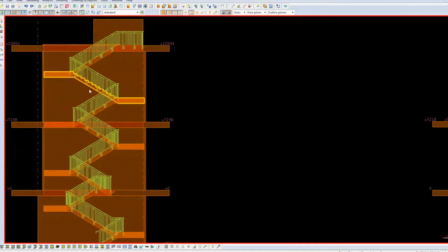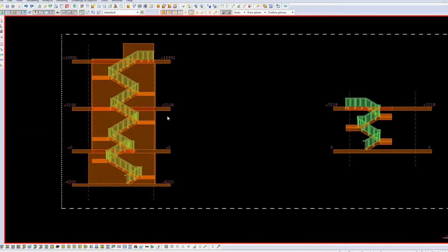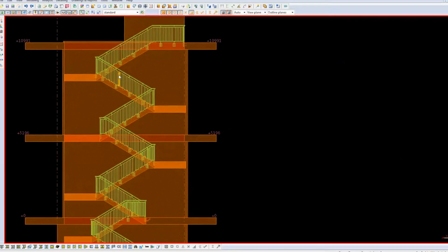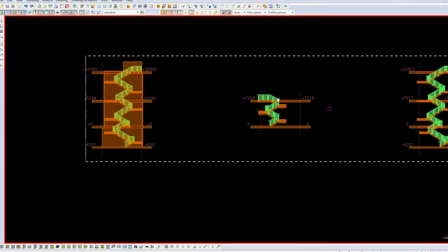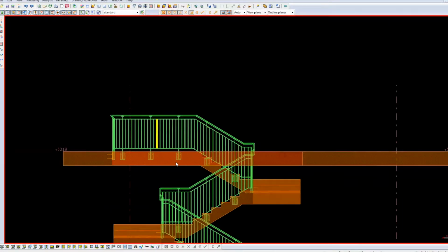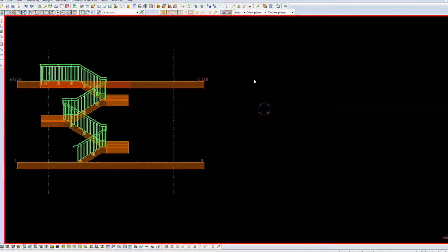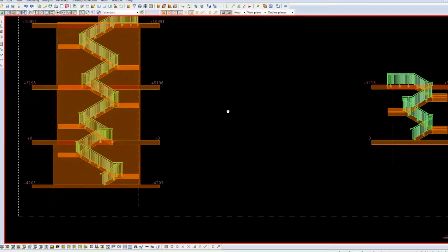So that's what I did. I did an exercise of justification, which I'll get into in a minute. Remodeled all this balustrade so that you had standard panels to be issued throughout. In actual fact, the variation on the angles was so great that I ended up with about 3 different standard panels over the 4 staircases. Obviously you're always going to end up with individuals in your returns.